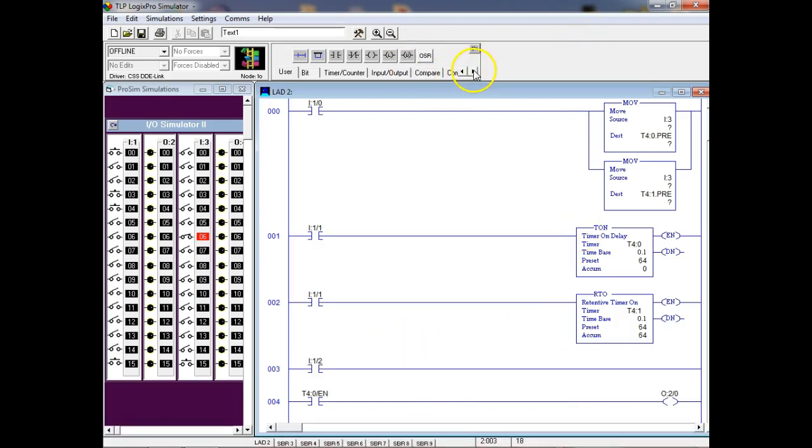And then we'll go back over to our timers and counters, and we'll put a reset instruction. So a reset instruction is considered a what? An input or an output? Output, because it moved to the right, right? And we're going to reset timer 4:1. Are we okay? So we'll use this guy right here, and I'll change it to a push button.